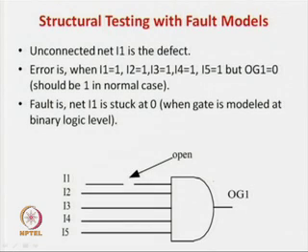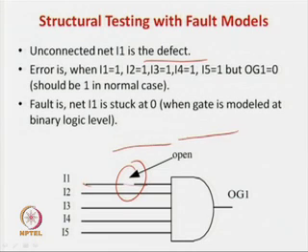So, this is an AND gate. We have already seen that a NAND gate is so complex, it can have faults at the transistor level and at the layout level, so a lot of faults can be there. For example, let us assume that this is a stuck open fault. This line is somehow cut, this input is somehow cut. This is actually called the defect: the layout is not proper, the metal should be like this, but somehow there is an opening.